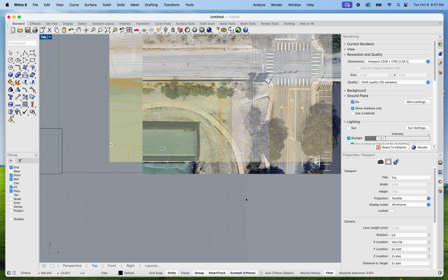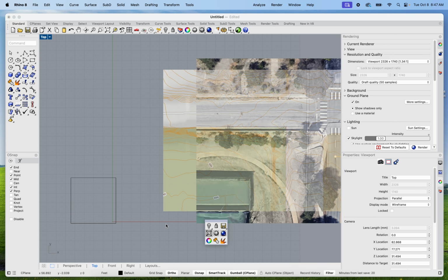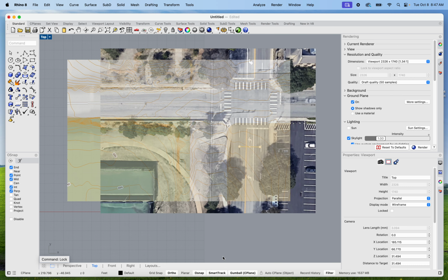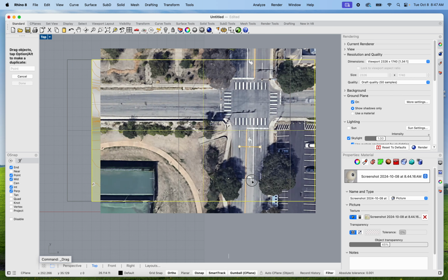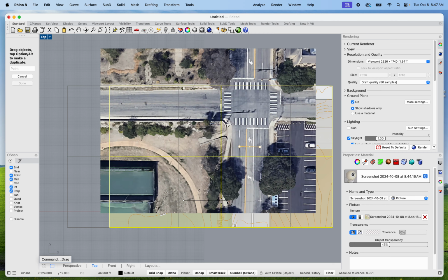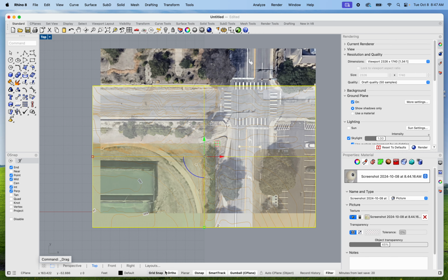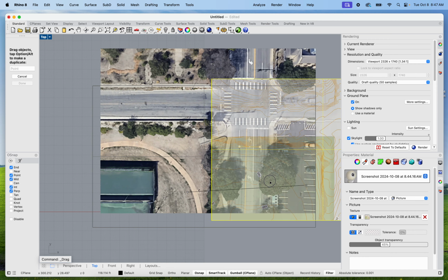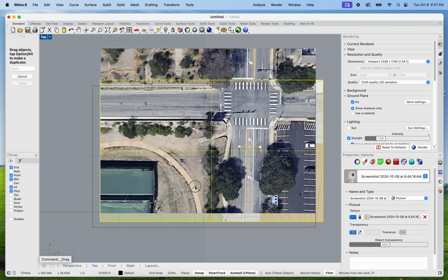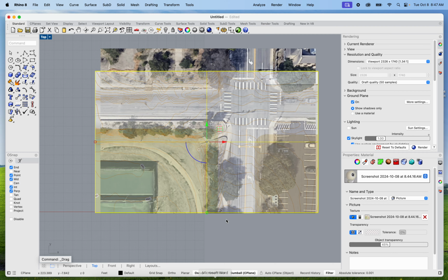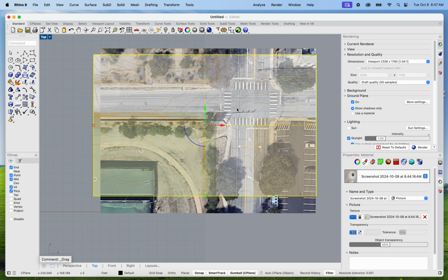And so I'm just going to arbitrarily at first, at least try to get them lined up. And one of the things I may have not gone over yet is being able to lock things and unlock things. Of course, I can just type in unlock, but I do find that a little bit easier, so that some aren't moving around while I'm trying to do things. Right now it looks like my grid snap is on of some kind, or ortho, that's what it is. So if your ortho mode is on, you'll notice you can only move in perfect 90-degree directions. I don't know if anybody's run into that problem, but sometimes your orthographic button is engaged.